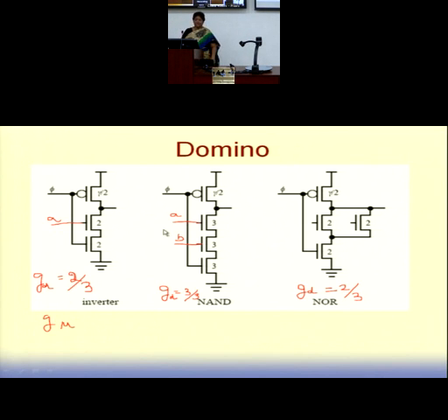So can you compute? Now if I design, it need not be 2:1. I need not have a pre-charge to pull down in the ratio of 2:1. It's not necessary. Because for my evaluation, I am only looking at my pull down transitions. Pull up is certainly only for pre-charging.